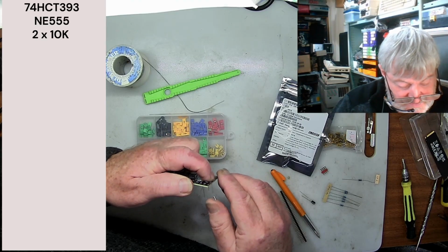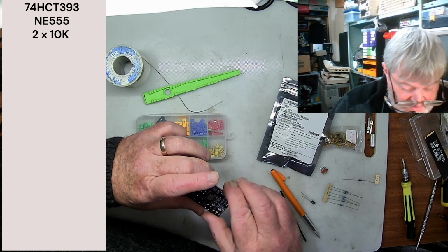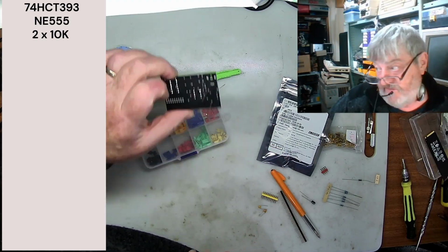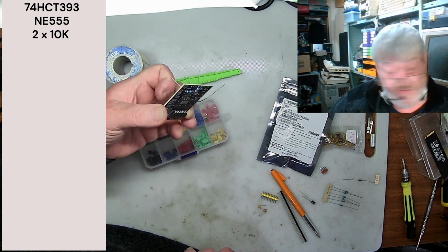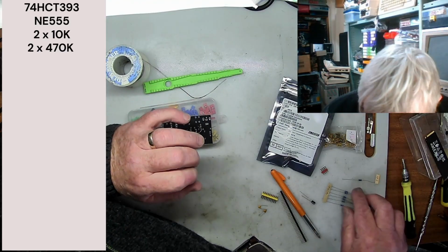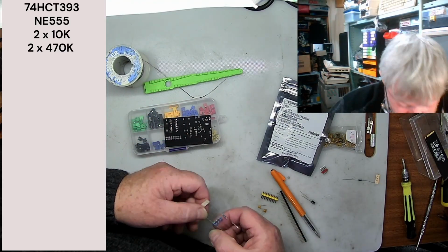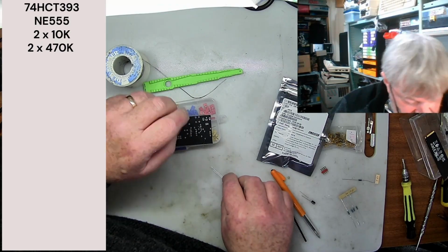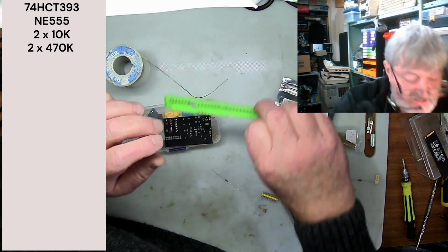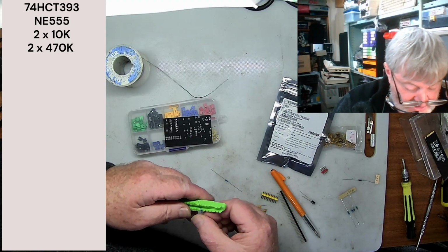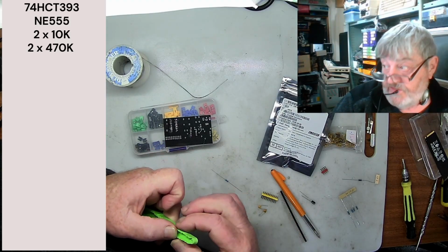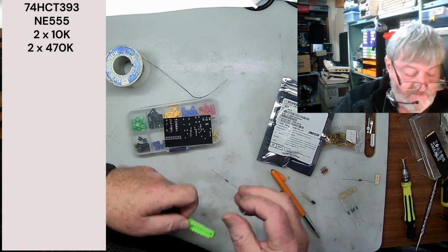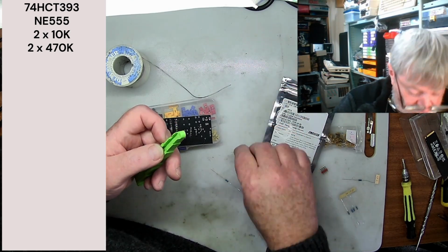Yeah, we just splay those out fractionally, and we get the 470s. And this is the good thing, if you splay them out a little bit, they're not going to fall out of your board. We get 470s, we need 2 of those. And as I say, I don't need these in the board because I'm not going to use the reset at this stage, but I will probably use it at some later date, and then it's good to have it there so I don't have to try and make a separate reset circuit.